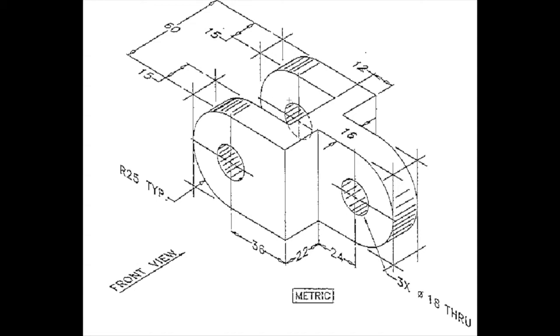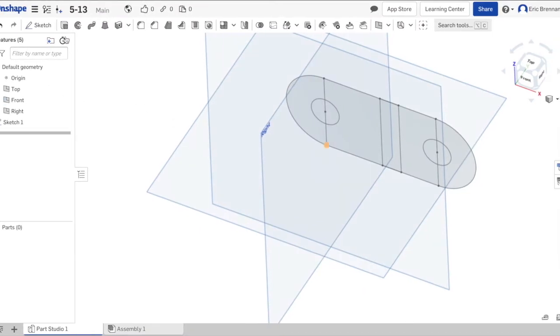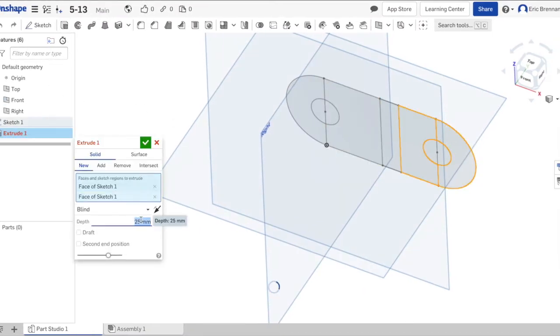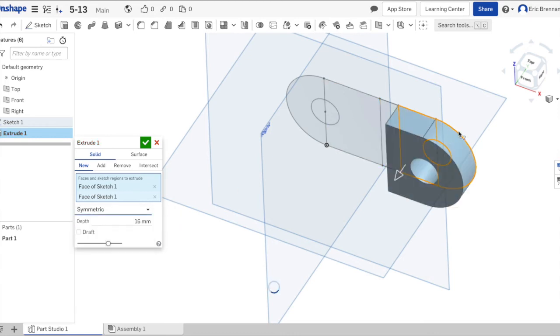I'm going to treat this as if it were a complete solid at first, so I can cut away material from the back side. This front side I'm just going to treat as one solid, so let's start here. That's 16, and since it's symmetrical through the right side plane, I'm going to extrude in a symmetrical way, and you'll see what I mean. So extrude. This is my first extrude. 16. And instead of blind, I'm going symmetrical.